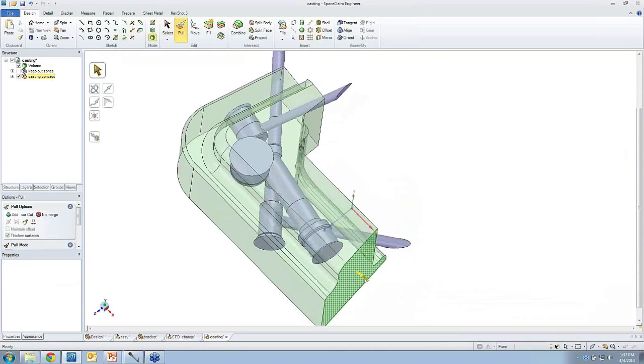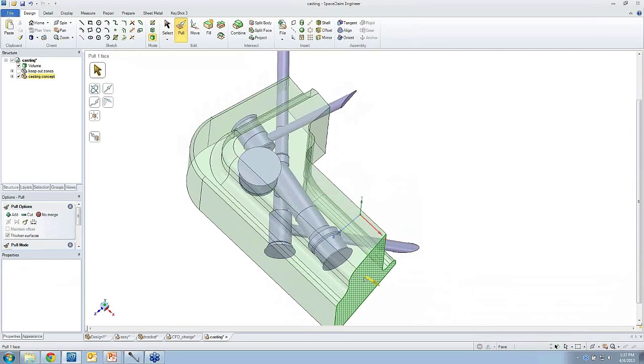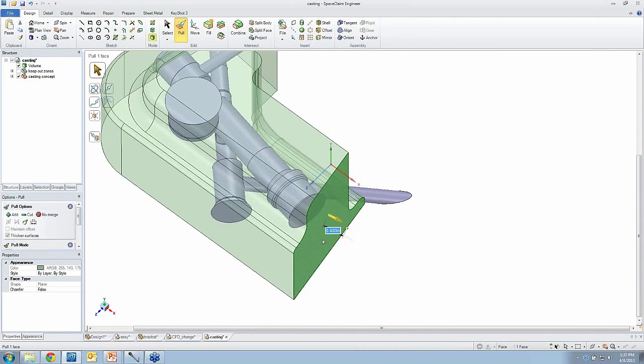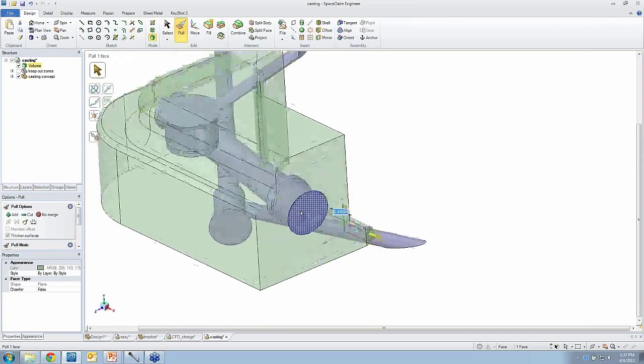and start making modifications to it. You see, I've counted 4 main ports. I'll select them all right now so you can see them. 4 main ports that need to have an opening, or the solid needs to have an opening available for all those. So that's where I need to start doing my modifications. Well, this is where the direct modeling tools in SpaceClaim just come in so handy. I'm able to snap faces up to those ports.